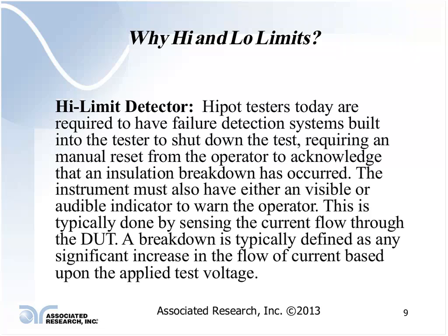High voltage was applied to the product, but the return lead was open. So now the product had 1200 volts being applied through the line and neutral conductors. The capacitance of the circuitry to the dead metal allowed for the enclosure of the product to have 1240 volts being applied to the enclosure.